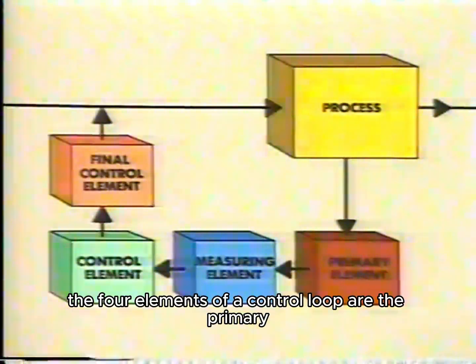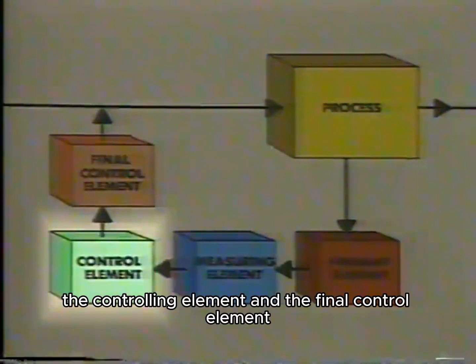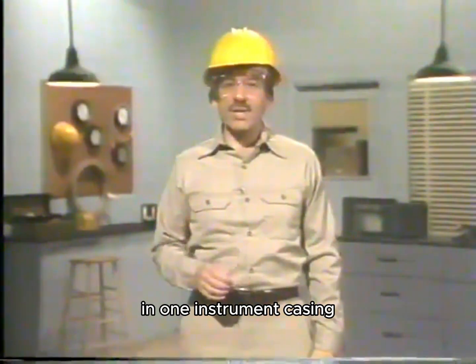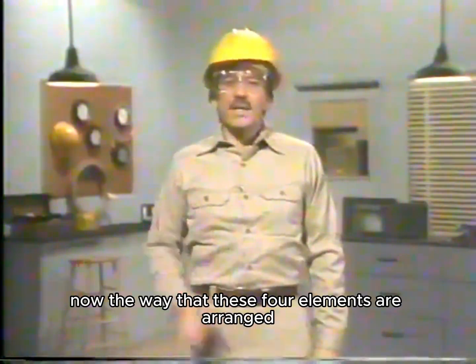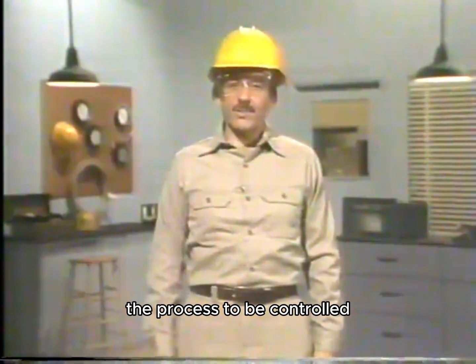As you may recall, the four elements of a control loop are the primary or sensing element, the measuring element, the controlling element, and the final control element. These four elements will be present in every process control loop. Now, in some loops, the primary and measuring elements may be combined in one instrument casing, or the measuring and controlling elements may be combined, but the four basic elements are present. Now, the way that these four elements are arranged and how they're utilized can vary according to the requirements of the process to be controlled.